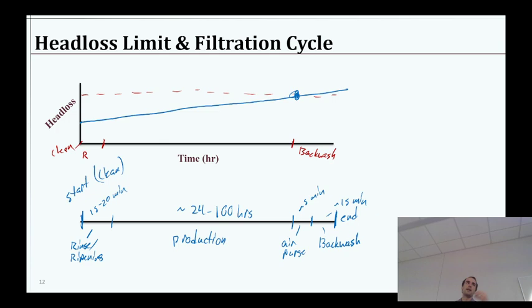But then we need to add in, okay, what volume did we subtract to backwash, and what volume went to waste with the rinse? We have to go through each of those pieces and have a way to put them together to say, oh, okay, if we need 15 filters in operation at any given time, that gives us space to have 4 other filters offline to do their rinse phase and all that.